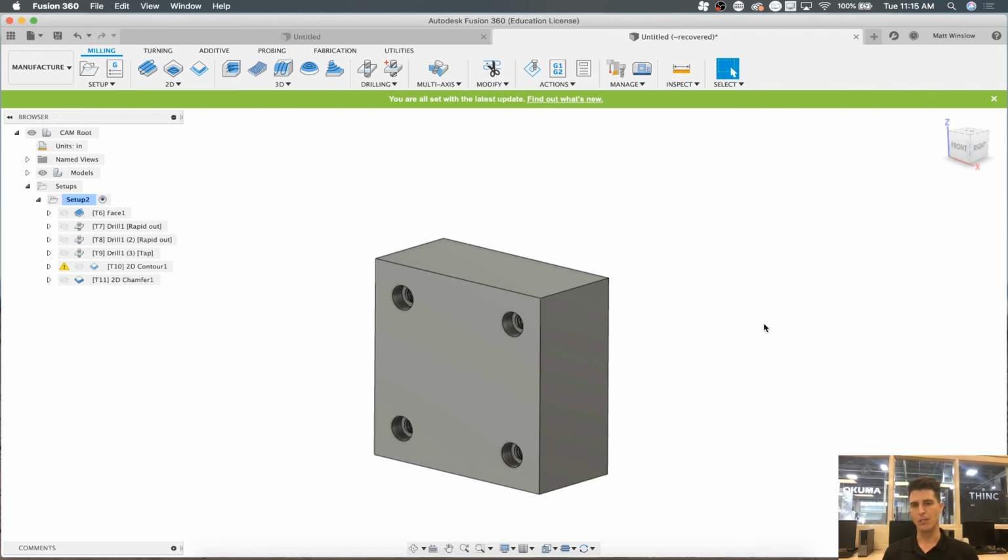So utilize our speeds and feeds sheet. Make sure that you're setting correct work coordinate systems and tool offsets out on the machine, and then triple check your setups out on the machine. And if you can, please do a dry run before you run anything. That's running things at least 3 inches above your part.